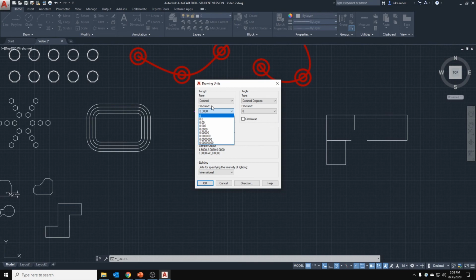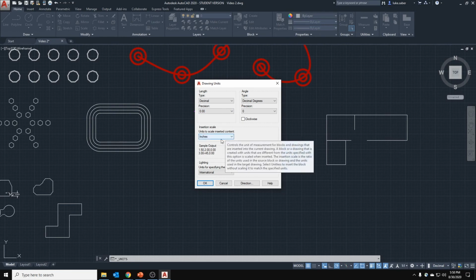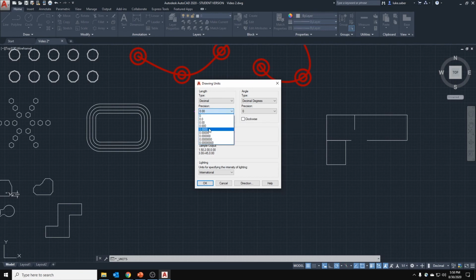And that's useful because a common one is an eighth, right? Something is an eighth of an inch. Okay, you might need that for something you're modeling or whatever it might be. 1/8 converts to, in decimal, 0.125. Now, if you have this in precision 0.00, you'll see not 0.125, but 0.13. Now, that could be misleading, so to make sure, it's always helpful to have extra units to show what you want, but maybe not too many if it's too much.